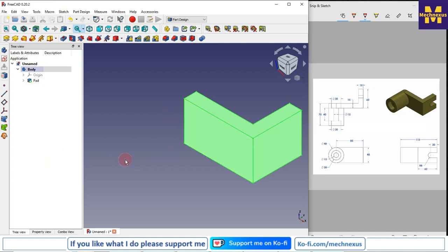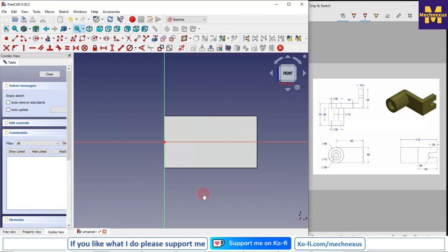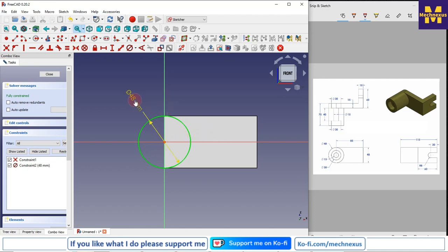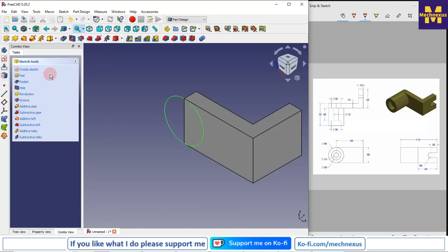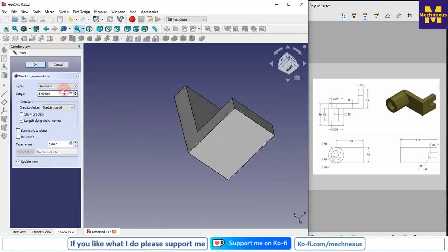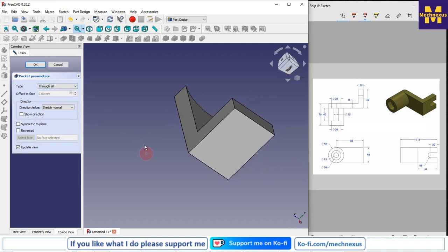So I will select this face and create a sketch, and this boss OD is 48. So I will draw a circle and give it a diameter of 48. Now I will come out of the sketch and I will go with a cut, and I will give it through all.